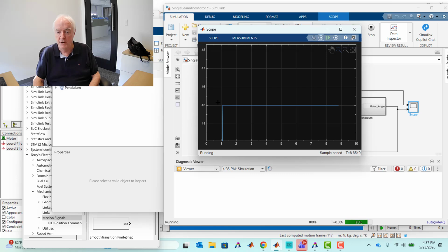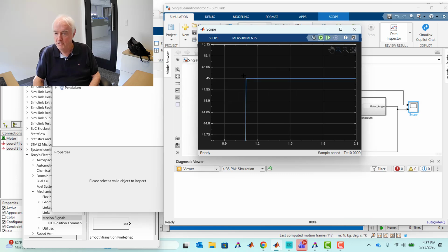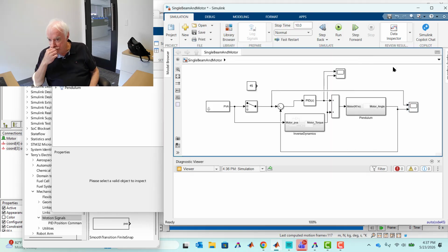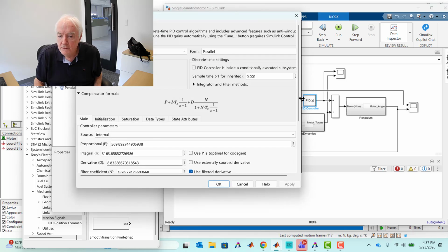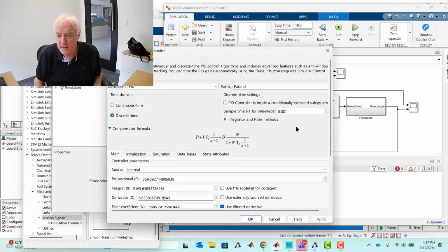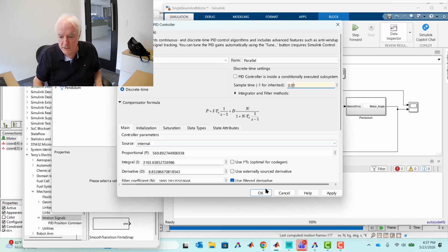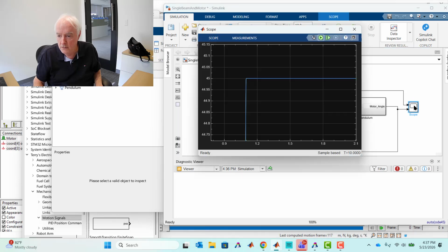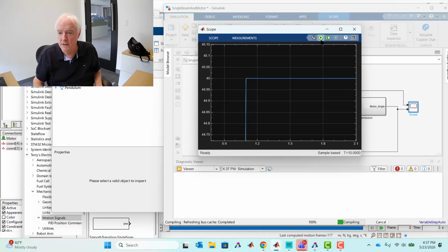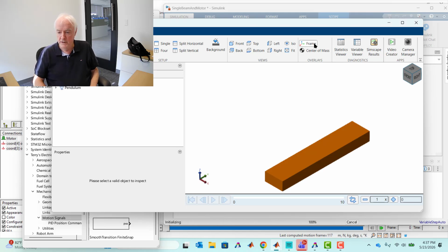And we got rid of that 1 degree overshoot. So we zoom in real close. That's way, way smaller than 1 degree overshoot. So inverse dynamics is really helping us there. I think the last thing I want to do on this one is that with inverse dynamics, we don't need that PID to be super, super strong and quite so active. And so what I want to finish on is let's reduce that sample rate to 100 hertz. Okay, we've already proven that we need a PID, but maybe we don't need a super active one.